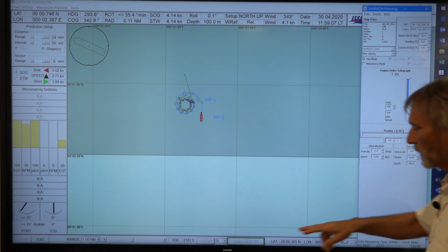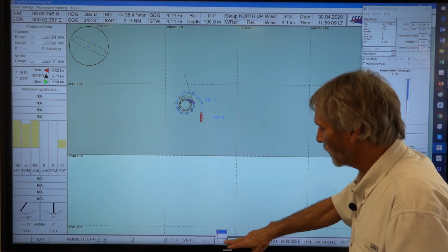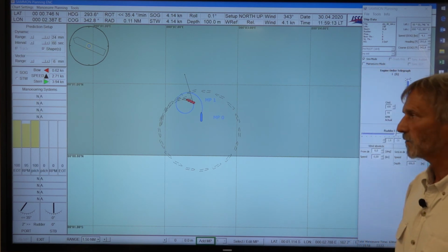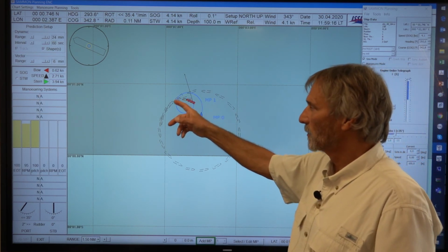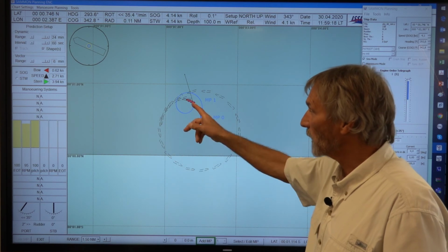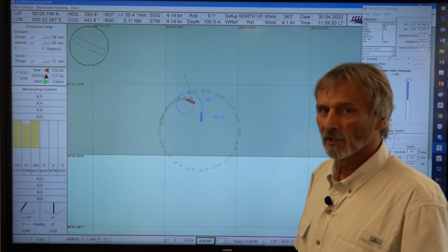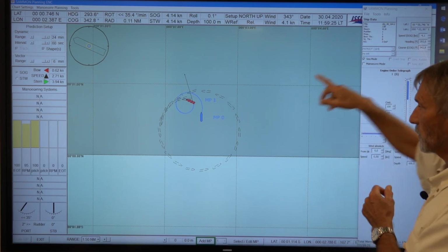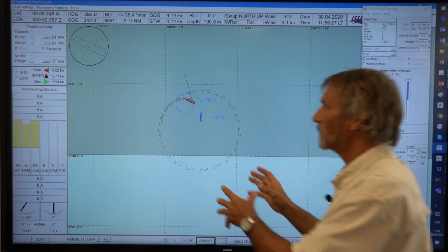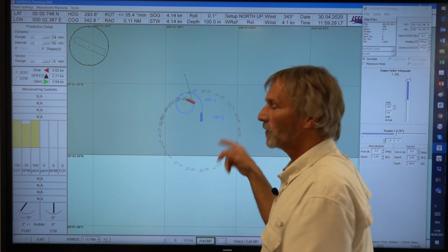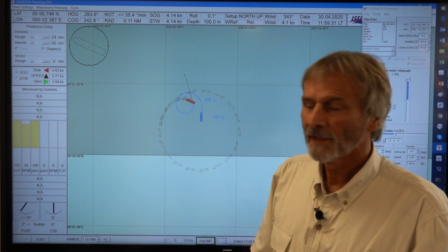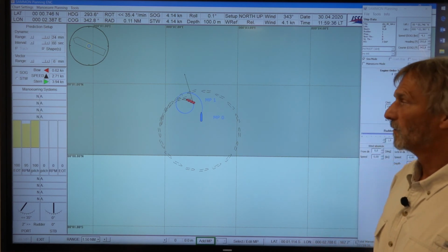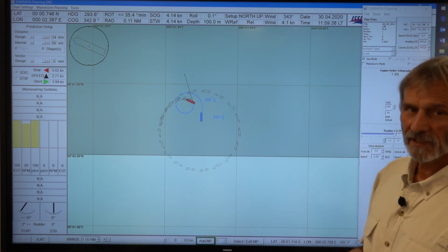And then we go to the next position where we put the rudder amidship, here. And you see the result. The ship continues turning to the same direction as it has before. So if we have a starboard turning circle as we had before, it continues turning to starboard. And if you start turning to port, then it continues turning to port side. So this is the typical effect for the unstable vessels.